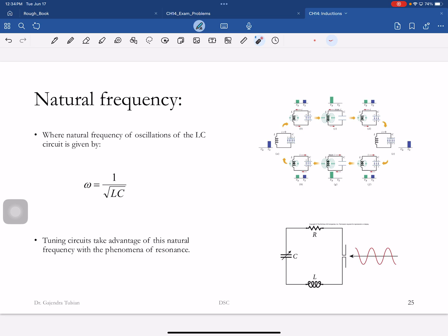Okay. So here's how you talk to this guy. Here's this basic tuning circuit. Here's the variable capacitor. Why is the capacitor variable? So you can change the frequency of this guy. So pick up whatever frequency you want to pick up. And unfortunately, we don't have frictionless devices, so they'll have some resistance. Here's the inductor. And here are rabbit ears to talk to the outside world.